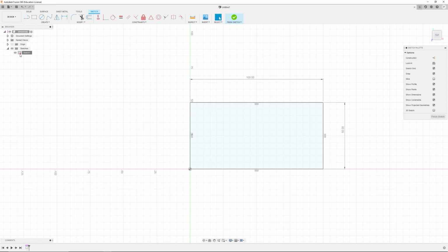If you do not have that lock on every sketch that you create, you will get marked down points. This is the biggest and frankly one of the only ways to lose points in this class. Make sure that you are fully defining all of your geometry as you go along. This is just best practice to get into immediately, and I am very firm about that.